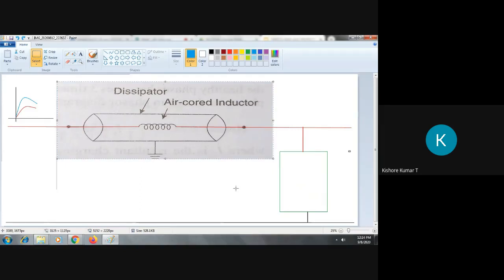This is nothing but insulation coordination. Only then, instead of the transformer getting damaged, this will get damaged first. We are just applying protection. If the insulation level of the protective device is high and that of the equipment is low, there will be much stress acting on the equipment to be protected, due to which the equipment will get damaged. This is what insulation level explains.